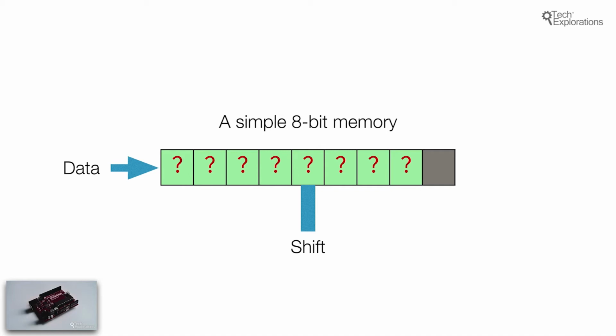To support the serial transfer of bits from the Arduino to the shift register chip, we need a second pin to provide a clock signal. Every time the clock ticks, one bit is transmitted from the Arduino to the shift register. Once the new bit is received by the shift register, all existing bits are shifted by one bit to make room for the new one. This shifting process is what gave the name shift register to this device. Here's a graphical way to look at this process.